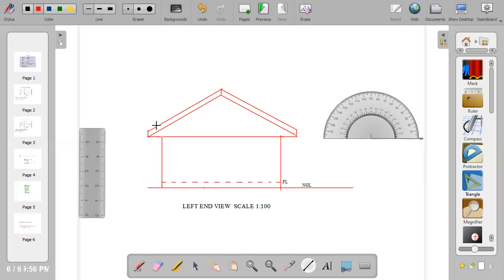Bring out the roof covering by projecting this line outward a bit. The roof covering will just project a bit outside the facial board. You can use 0.1 or at most 0.2. Then use it to bring out the thickness of the roof covering, which is no more than 0.1. Do it towards your left hand and take it through your right hand side.